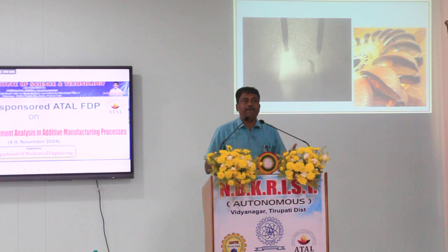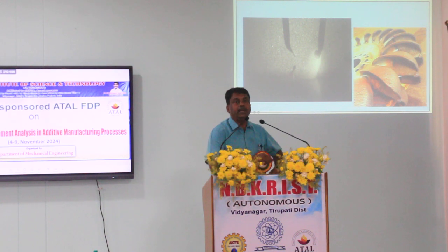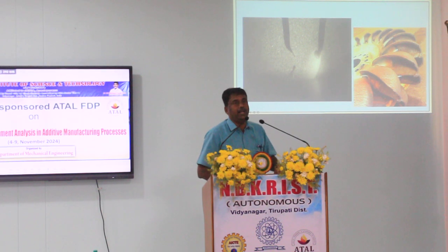So the advantage of using welding-based processes is that we can also modify the composition of the molten pool through dilution. Right, so in this example, what I showed is an impeller used for a Navy application, which we built in collaboration with a university in Australia.